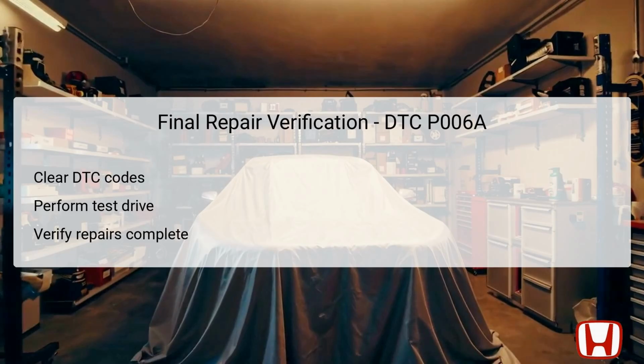After completing the necessary repairs based on the diagnosis of P006A, it is critical to perform a final verification. This involves clearing the DTC codes from the system using the HDS and subsequently taking the vehicle for a test drive. During the test drive, monitor the engine performance closely, ensuring that any previous symptoms have been resolved and that no DTCs reappear. Assessing the vehicle under various conditions, start, stop, acceleration, and idle, will provide confidence in the efficacy of the repairs performed.